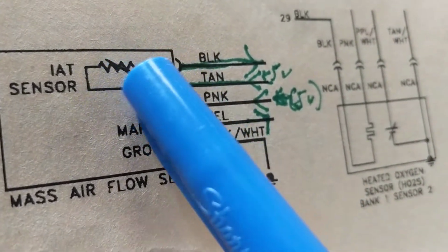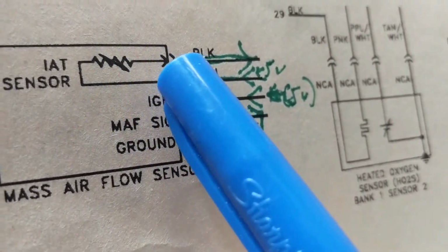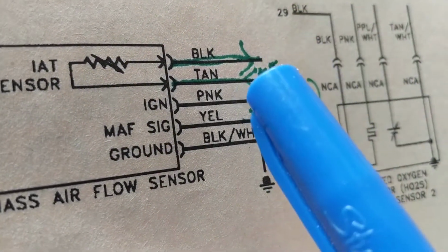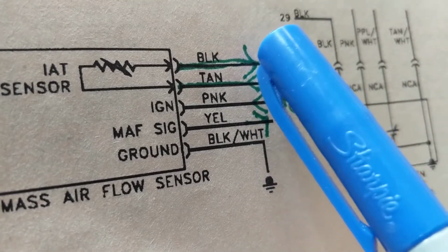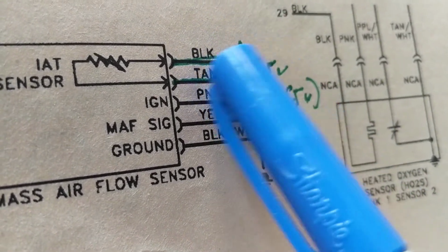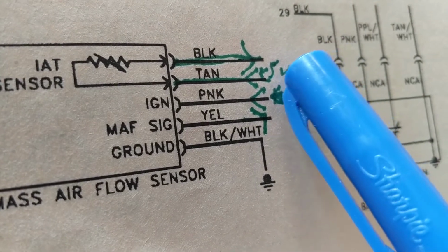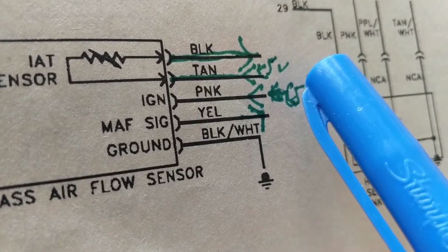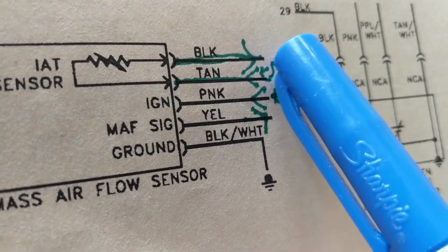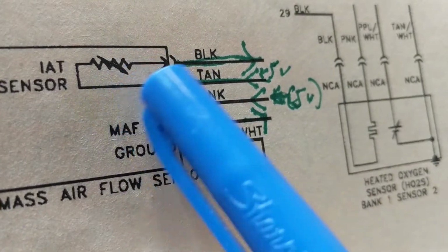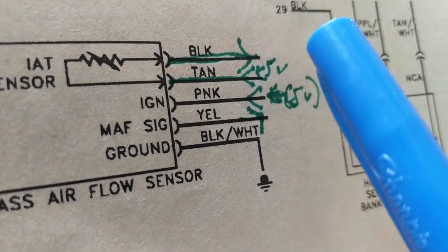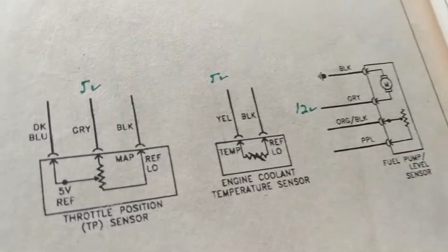What about this one? This is also a resistor, the coolant temperature resistor, intake air. All these are resistors that change value. Where do you think this one goes, where I put the arrow going out? The computer. The computer has to give 5 volts, the tan line, you see this going in, and it has to go out giving the information of the temperature of the air. So the computer giveth, and the computer taketh, like they say, right? It doesn't matter what type of sensor.